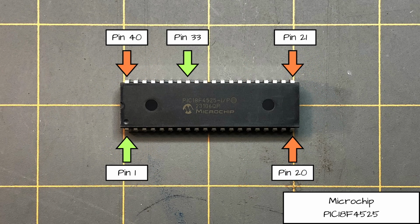So RA0 means bit 0 on port A, and RA1 means bit 1 on port A. Port A is one of the I/O ports of the PIC 18F4525 that contains individual I/O pins for that port.